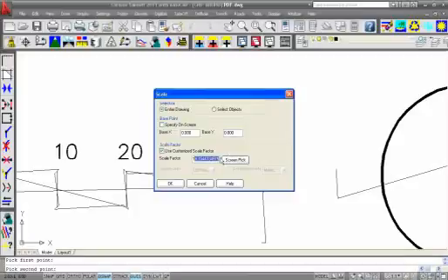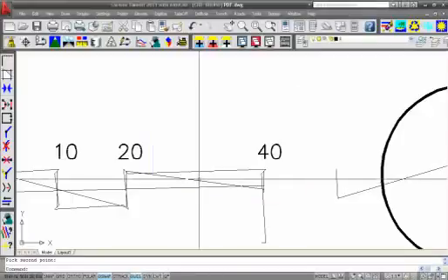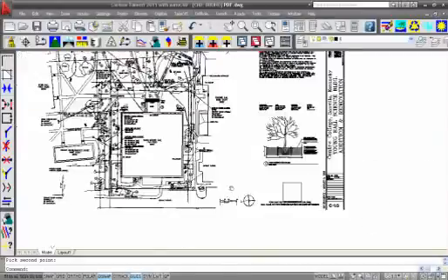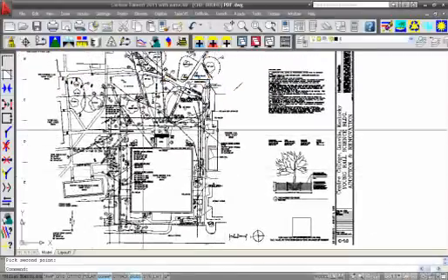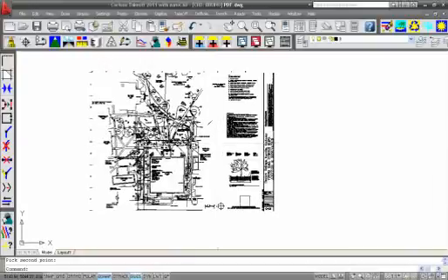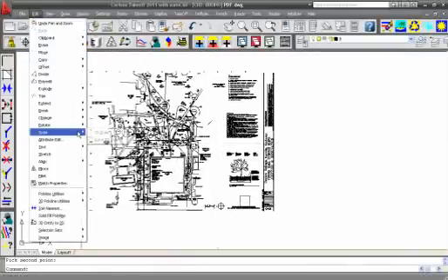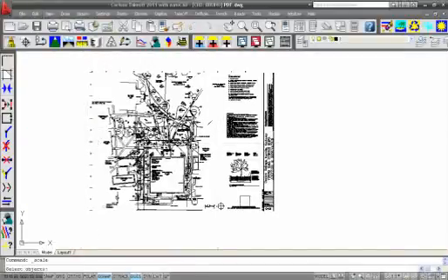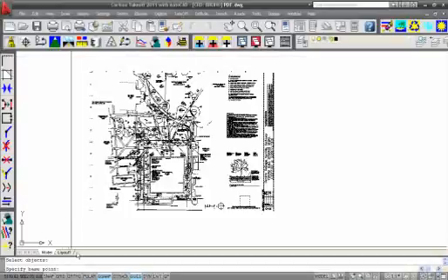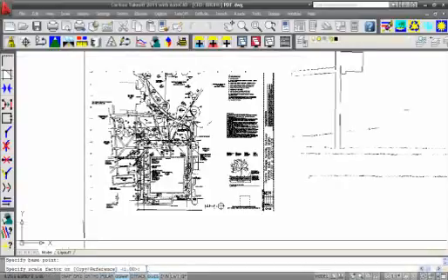Just for time purposes, I'm going to use the other scale. I'm just going to copy the scale and say cancel. The 2D scale can take a long time on a drawing this complicated to convert it. So I'm just going to use the AutoCAD scale and use that factor. Okay, select objects, base point, and paste in that value.